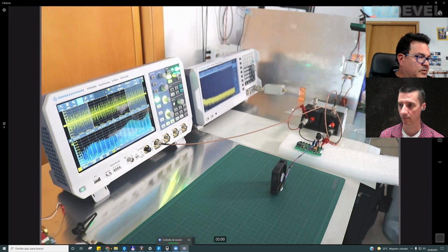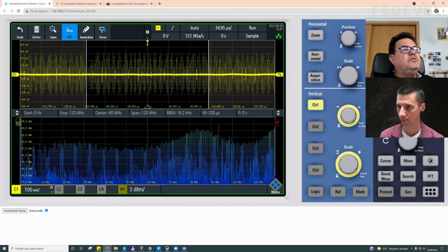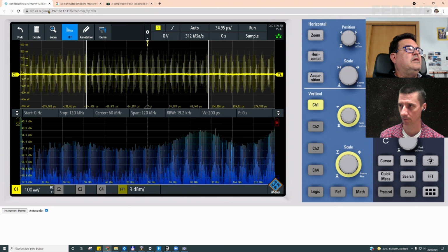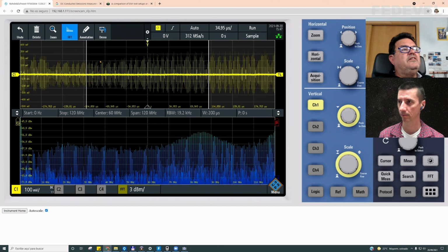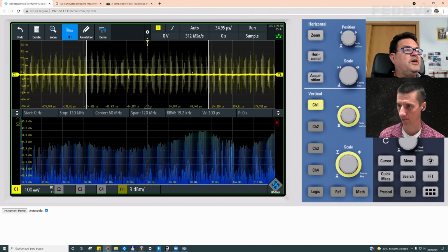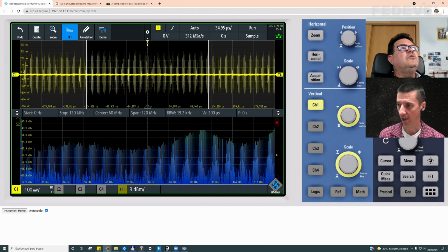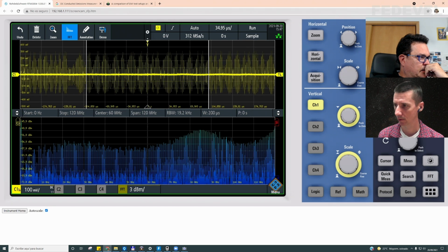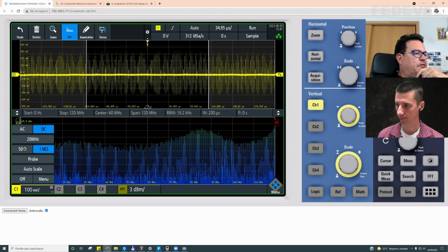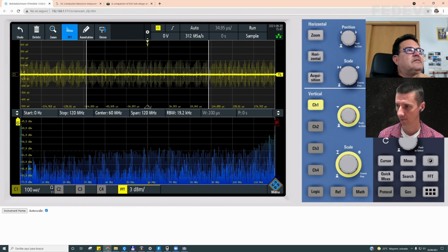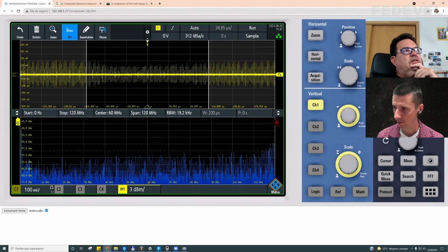So this is the same screen you see here with the camera. It's in the software. This is not a software specific for the instrument. With the IP address, you can access directly the software that is internal to the instrument. And then you can see the spectrum of the signal in this frequency range. But we need to check, is the 50 ohm switched on? Now it's off. So you can see the difference if I switch it on. That is different. So you need to try to avoid this error.